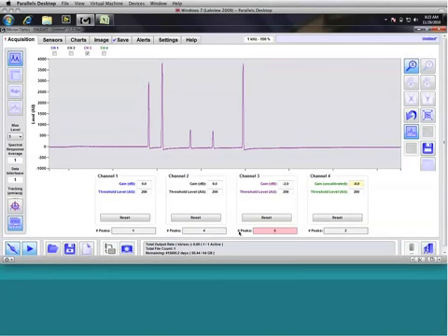Okay, so essentially, the ENLIGHT application and the SM130 had established when they first made a connection that there were 0 spectral peaks on channel 3. Now we've changed that situation proactively, and so we need to go and tell the application to resynchronize those peaks or to reset wavelength tracking. And I've highlighted that control down here on the bottom left.